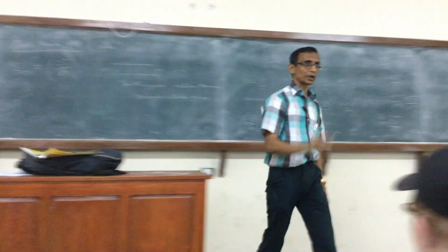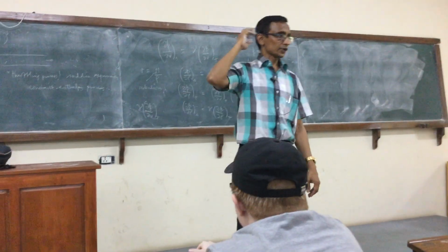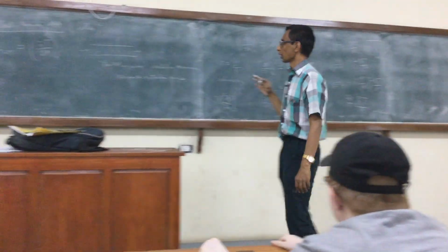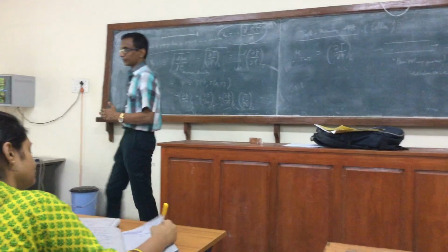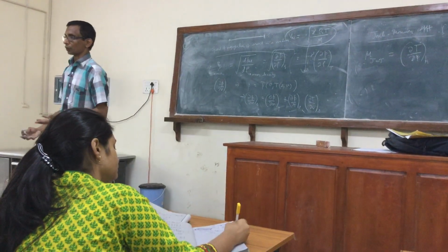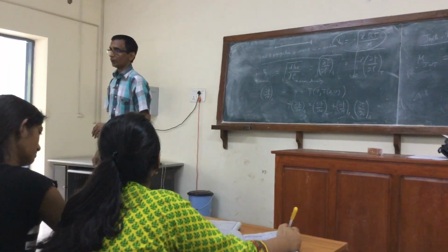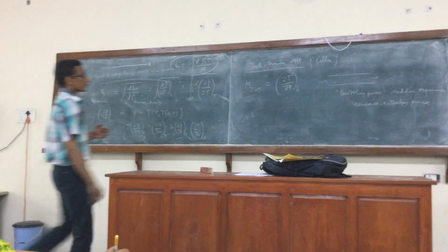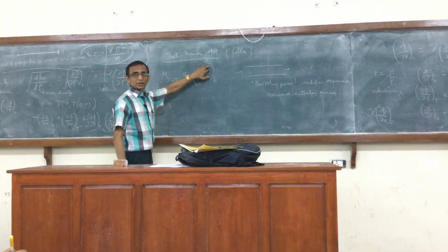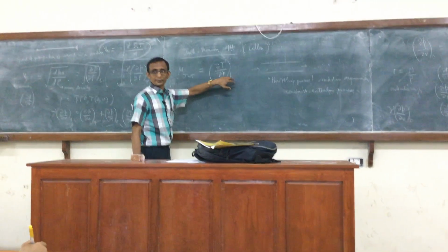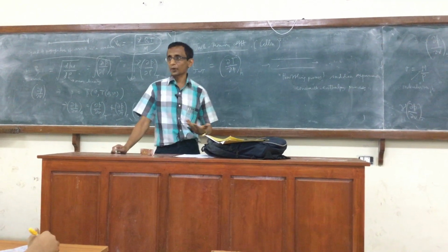We don't get into the derivation of that, because it will require the first law for flow processes, which we have not yet considered. So it is given to us as the Joule-Thomson coefficient, and we want only to estimate the coefficient. So dT gives the change in temperature for a change in pressure. This is a constant enthalpy process.